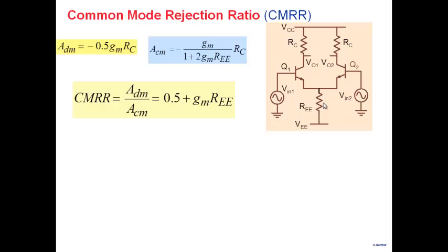What about the bias current? Bias current will go down. Right? Bias current will go down because remember what is the bias current? Minus 0.7 minus VE divided by RE. So if you make RE large, then the bias current will go down. And if the bias current goes down, then GM also goes down. See, it's not as straightforward. So what we can do is we can write down the expressions here.